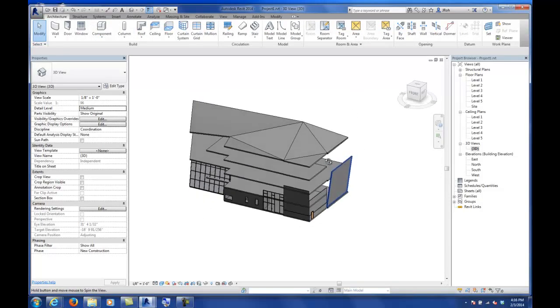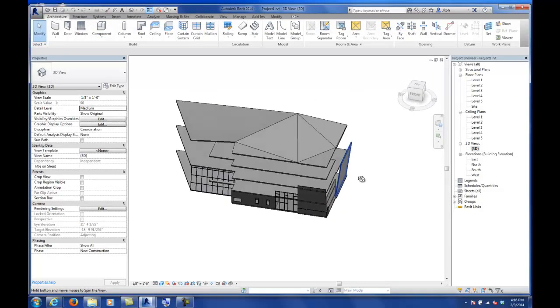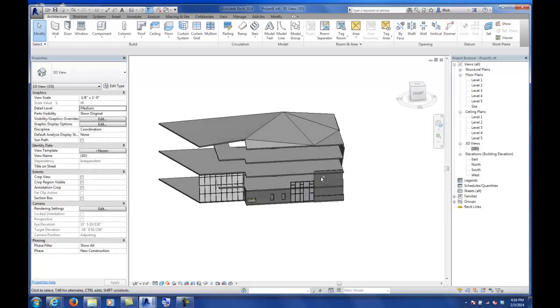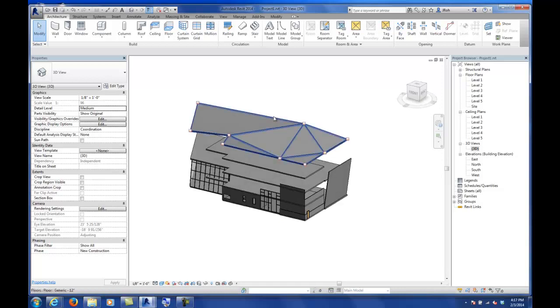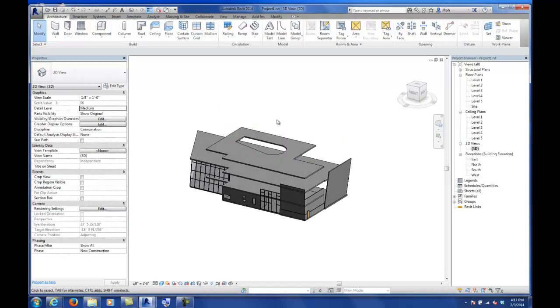So you can start to manipulate your ground plane, your particular floor plan by these kind of points and parts and pieces, and it's going to define as best it can by triangulating your surface and trying to connect those other points. And at any moment you can pick these other points and then also assign them different heights and so on. I'm going to delete that and keep our level 5 datum. I'll hit save.